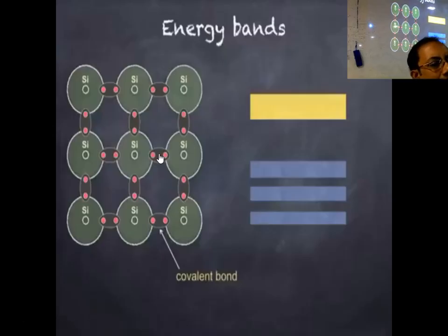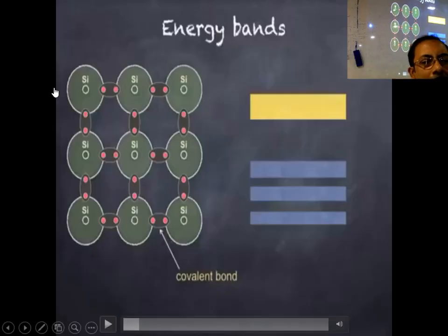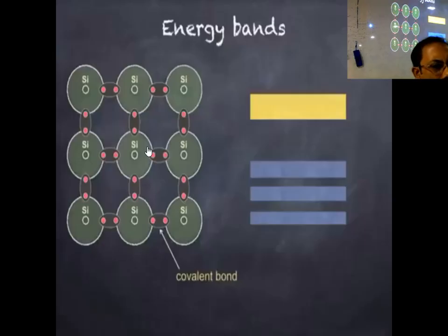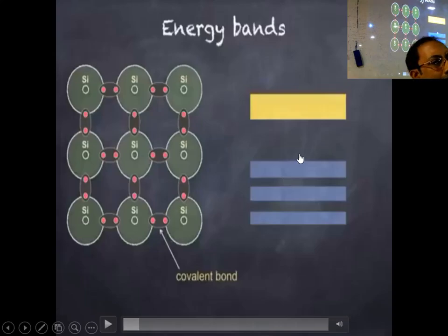That is the reason it acts as a semiconductor, because some of the bonds can be broken. If the bonds are very rigid, then it could not become a semiconductor. That will be a non-conductor. But here some of the bonds can be broken by some amount of heat supplied, and that electron is freely moving. When the bond is broken, it becomes a free electron. So this electron is displacing, going into the interstitial positions, and then the electron can freely flow. And at a bit high temperature, maybe 100 degrees or so, this acts as a semiconductor.